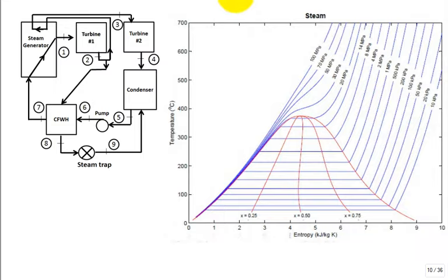Let's go ahead and sketch the whole cycle out with a trap. Let's go about 450 degrees C. Let's go around 8 megapascal. There's state 1. Let's put it down to about 1 megapascal. Right there. There's state 2. Let's not worry right now about the feeding of that closed feed water heater. Let's go and reheat to maybe state 3. Maybe it's the same temperature, maybe it's a little less. Then go down to the condenser. I think that's 20, that's state 4.